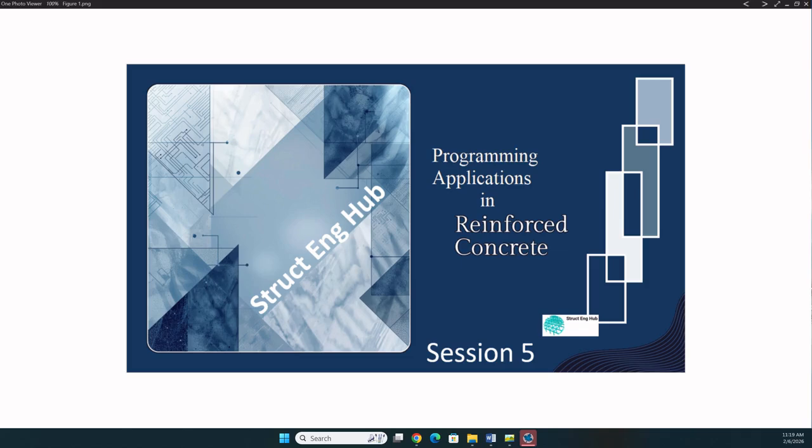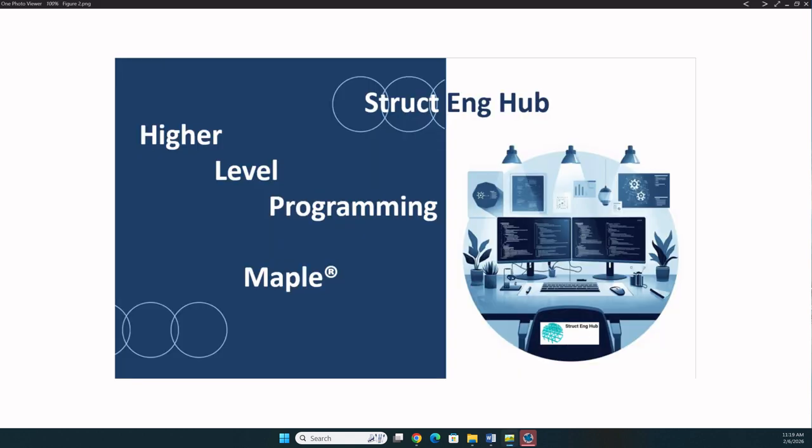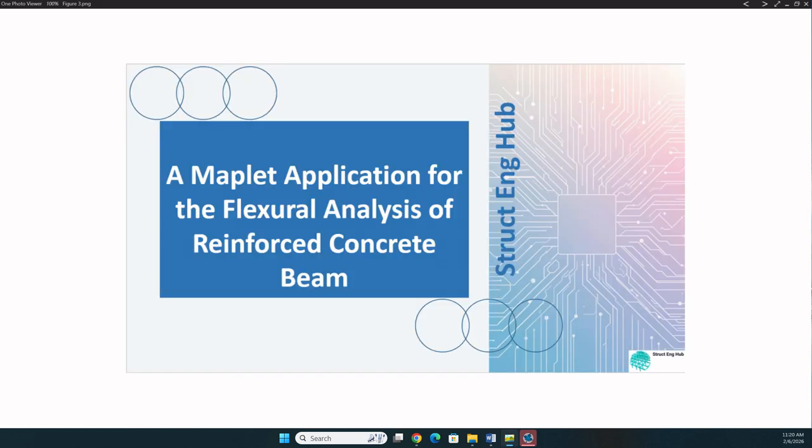Hello everyone and welcome to session number 5 of this set of videos created to explore programming applications in reinforced concrete. In this session, we will not use a Maple worksheet, document or workbook. We will use a Maple Maplet that I built from scratch to combine all the beam flexural analysis cases that we have dealt with so far, namely singly reinforced rectangular beams, doubly reinforced rectangular beams, T or L beams carrying positive bending moment, and T or L beams carrying negative bending moments.